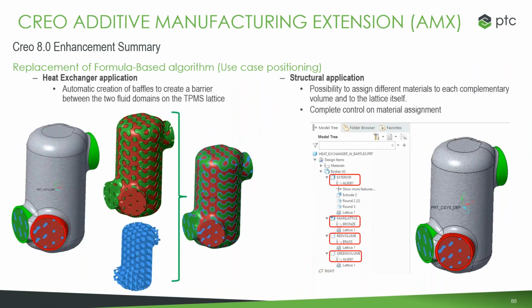Here's an example where you might be building a heat exchanger. You've got two different temperature liquids coming in, whatever they might be, and you're building some sort of 3D printed baffle inside that. Then you can create the bodies that represent the fluid from each of those two different inlets, to use downstream for your fluid simulation or thermal calculations. So it can automatically create those additional bodies as you're creating these complex lattice shapes.